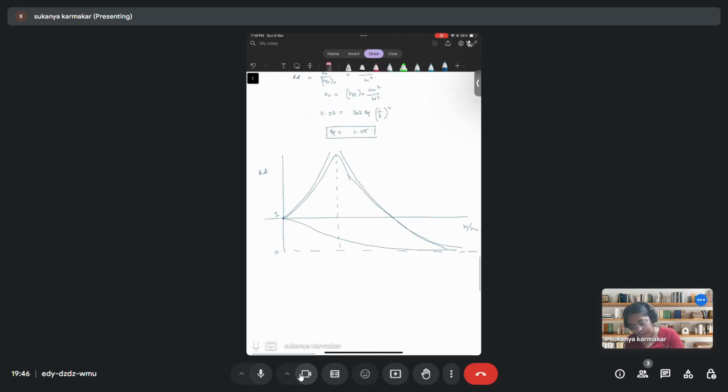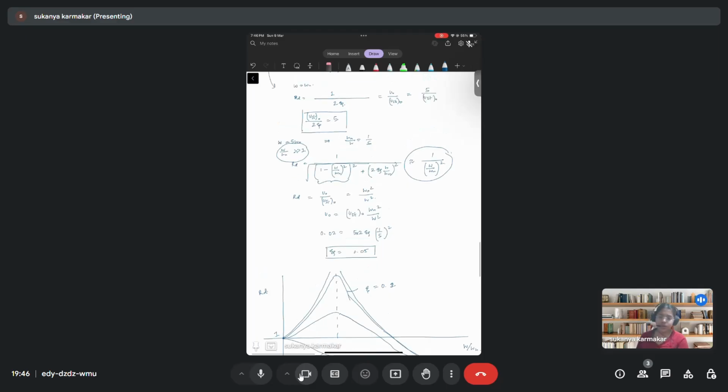So this is when your damping is 1, and here when your damping is, let's say, 0.01, and as you increase damping, your response will go on decreasing like this. So this is how this response reduction, deformation response factor is used. Then we had already discussed this half power bandwidth method last class, so I'm not repeating it.